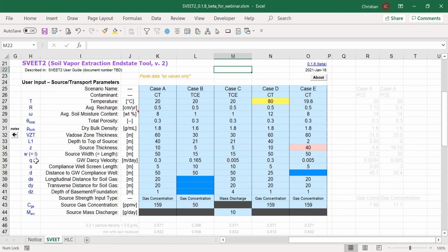The groundwater velocity is another one that can have a significant impact, because if it's very low, the mixing into groundwater is much more. You get a higher concentration versus higher velocities. You're going to have lower concentrations as the groundwater moves along. So that's a little mix of answers, but hopefully it gives you a sense. It's about the transport of the contaminant, and then the source strength kind of controls things overall.